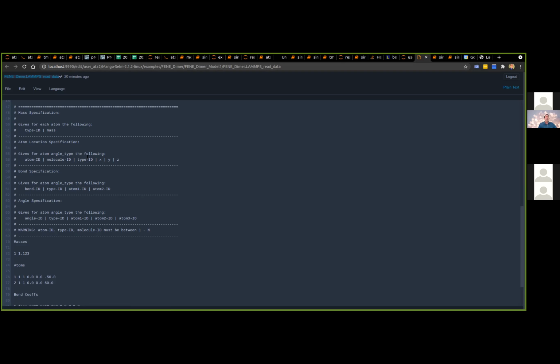And then what type is it? The type, of course, is going to refer back to the mass, charge, other attributes you'd want to give to those atoms. Again, you can have XML-related parameters as well. So SELM can put additional information on the atoms. Like you can say, all the atoms with these indices are of this structure or have this particular interaction for the SELM code. You can do that perfectly fine. This is just the LAMMPS side of things and how it's going to bookkeep. Then you have XYZ here, which is just the location. So that's how the atoms are going to be specified.